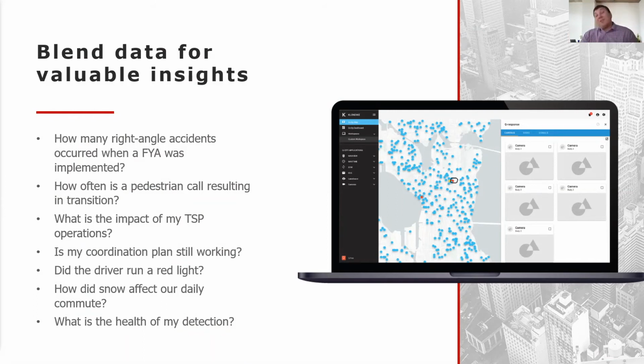But I think what's even more rad is we could tap into some of these video manufacturers' data where they're tracking pedestrians via video. And then we could start to say how many pedestrians were standing on the corner when transitions occurred. And if I find that I've got a ton of pedestrian loading at that intersection every time, maybe it's time to revisit my traffic signal timings, optimize them so I'm not throwing myself out of coordination every time I have a ped movement, right?